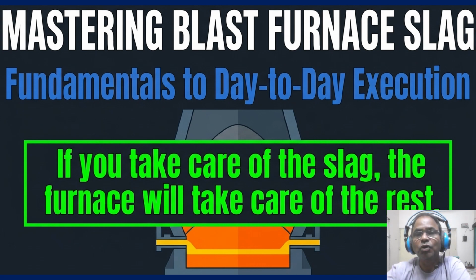Now, why should we care? There is an old saying in the steel industry: if you take care of the slag, the furnace will take care of the rest. That's not just a catchy phrase. Slag controls sulfur removal from hot metal, silicon content in the iron, alkali balance to avoid shell buildup, and permeability of the body and stack. So every time you adjust flux, you are directly taking care of the furnace. Let's move on.